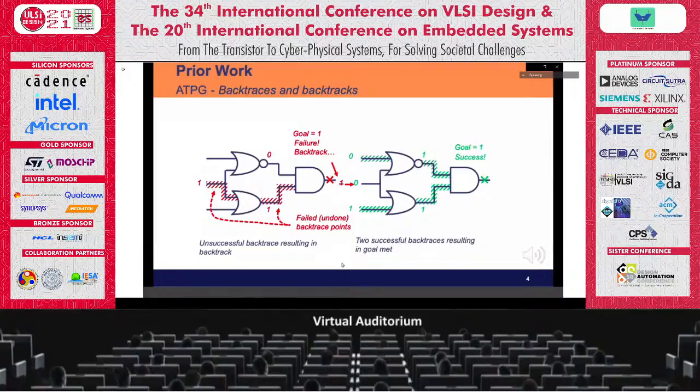However, this ideal situation presumes no backtracks occur during ATPG. When the backtracing subroutines reach a circuit input and assign it a value, this assignment may block the current or future objectives. When this occurs, ATPG must undo or backtrack to some previous assignment, which means ATPG wastes time simulating unnecessary input vectors. Beyond PODEM, numerous ATPG algorithms attempt to reduce runtime by creating fewer objectives, but to our knowledge, no studies compare ways of backtracing from an objective. When backtracing, it must decide which direction to go, but choosing a wrong direction may result in a backtrack.